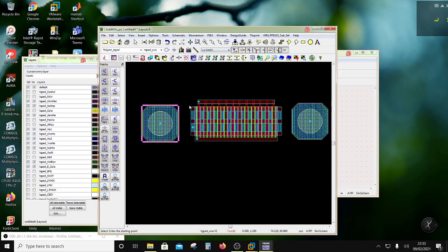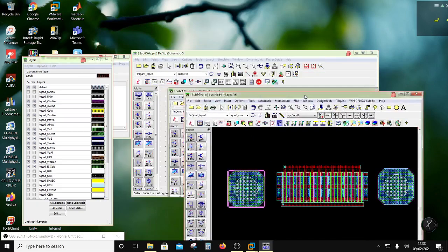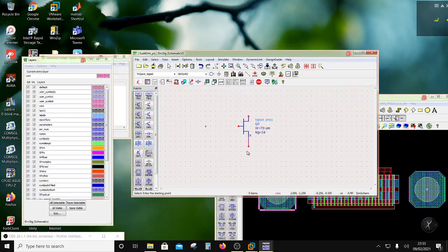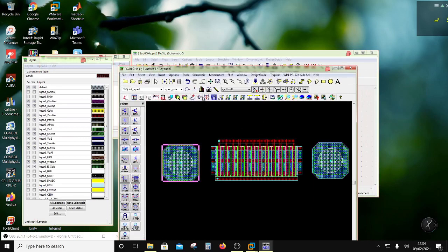Now if I put these two vias, I must know what the ground inductance is. And that inductance I'm supposed to put here, and that way my input and output impedances would be meaningful. If I directly put a ground here and then do the matching, then I have just wasted my time, because in practice a perfect ground will not be there. So the key in a common source design for your gain stage is to figure out what the inductance is in the ground, and that basically means that you have to put this via here.